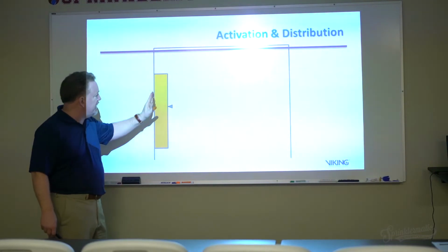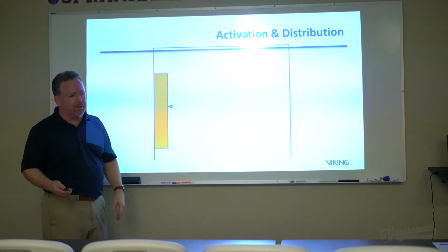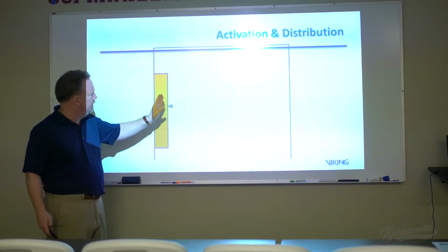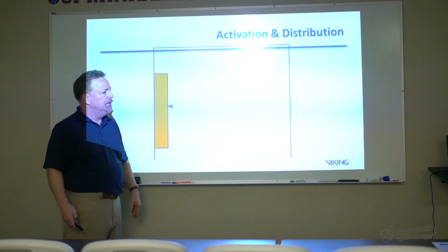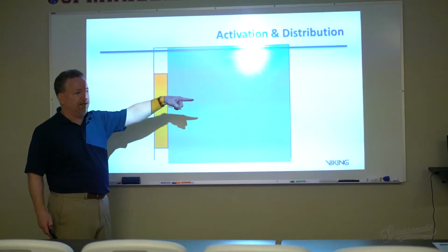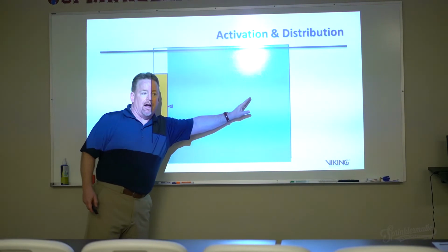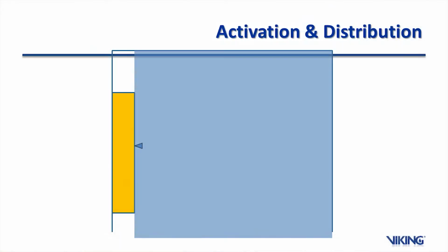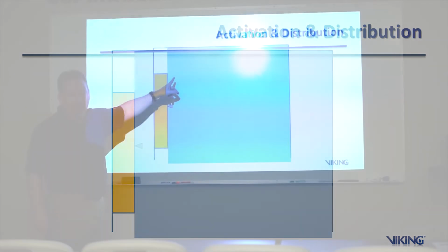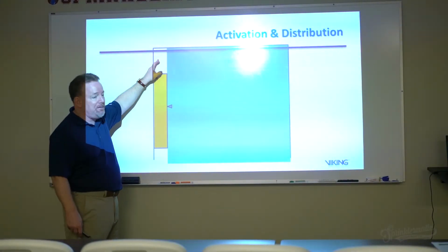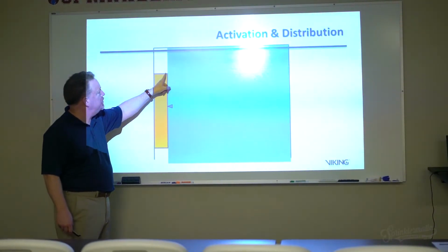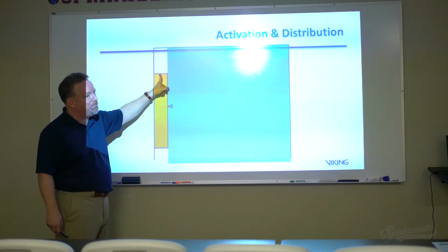So if I've got a sidewall sprinkler, where's the spray pattern going? From here, over, right? Now on paper, what does this look like? A shadow area, a space that's not going to get any water in. So sure enough, I looked around the corner. This is only about 15 inches deep right here.